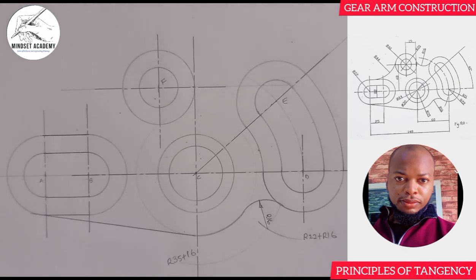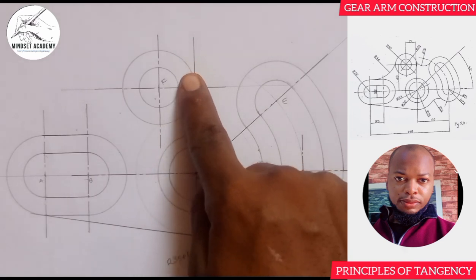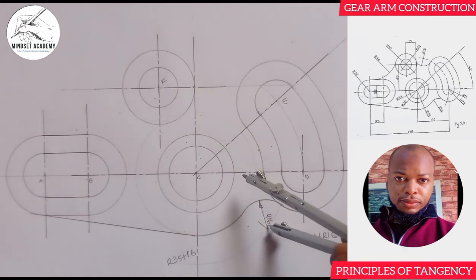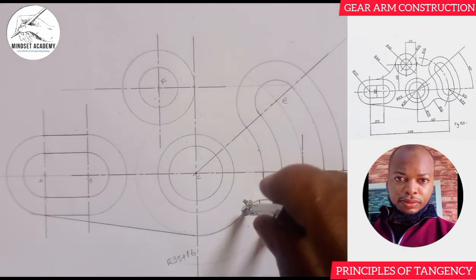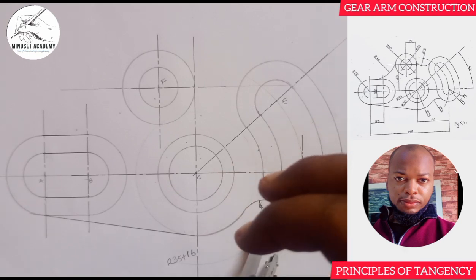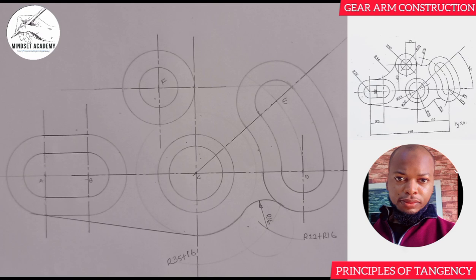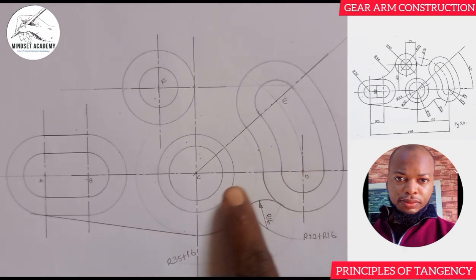So the next one that we have here is another one here again. Hope you've seen our arc here. There's an arc here also that's connecting these two together, and it's also going in, so we are going to add. Why are you adding? Because this arc you see here is external. Whenever you have any arc that is external to a circle, you say that what? Look at what I'm showing you on the screen is external. So you are going to add the radiuses. That means the arc we are considering is external to the main radius.